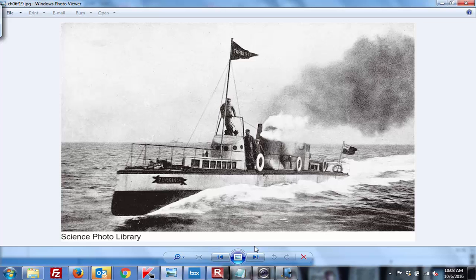30 meters, 100 feet long, less than 3 meters wide, and less than 1 meter of draft. So it's like a turbine torpedo. She was driven by 3 turbines in triple compound arrangement, delivering a total of 1.7 megawatts, 2,300 horsepower, to the screw propellers. Taken in secrecy to Cowes, she roared out into the 1897 Jubilee Review of the Fleet at Spithead with Parsons at the controls, traveling, it is said, at the unheard of speed of 33 knots.